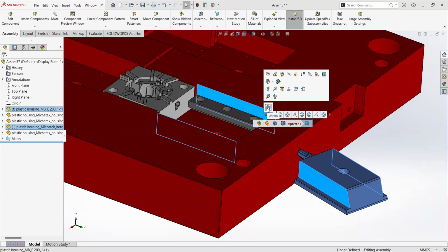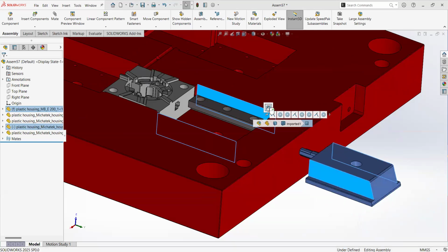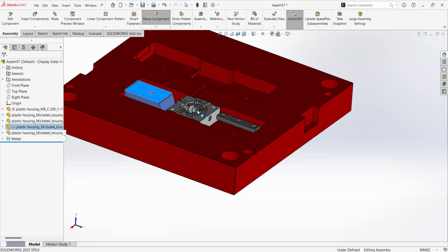So the option is the command width that I mentioned. So it is like kind of an in between, let's say, the faces. So it's the combination of the faces that gives me the alignment, let's say. So as you can see, the part is just constrained, or it's having a pending constraint, let's say, in the Y direction. So it is free to slide as expected.